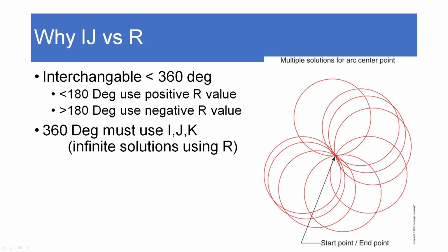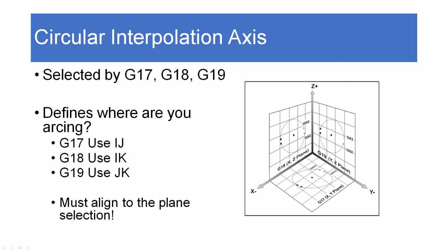So now let's go ahead and take a quick look here at these planes again. As we look at our mill, looking down at the mill, we're standing right in front of the mill, where my cursor is flashing. And this is our normal machining method. We're basically machining in X and Y, and we're arcing in X and Y.